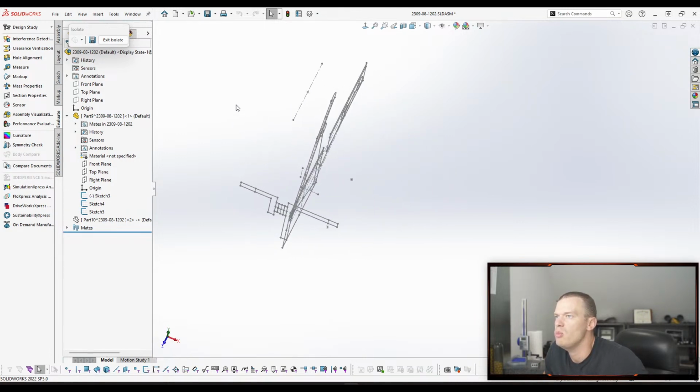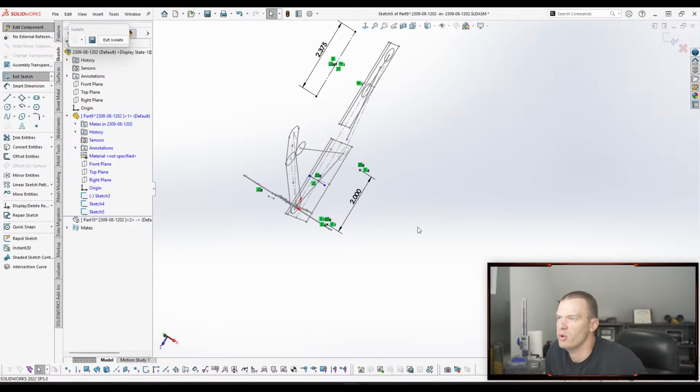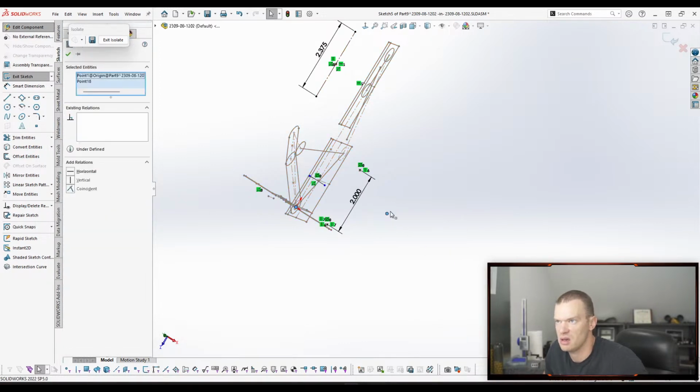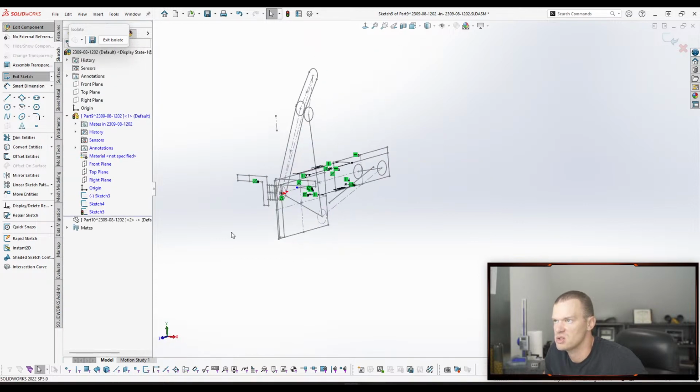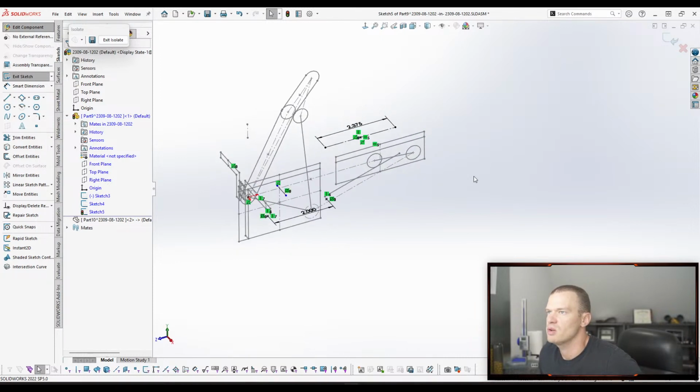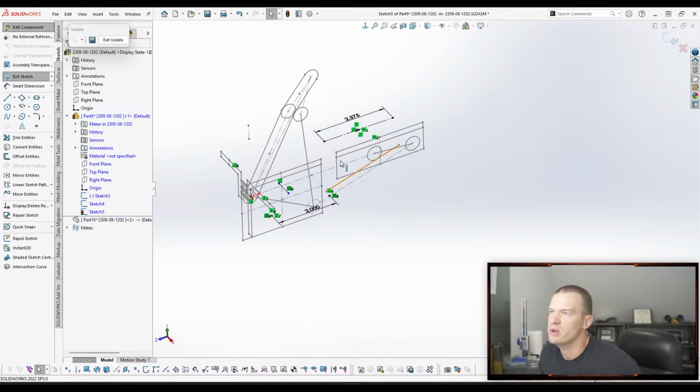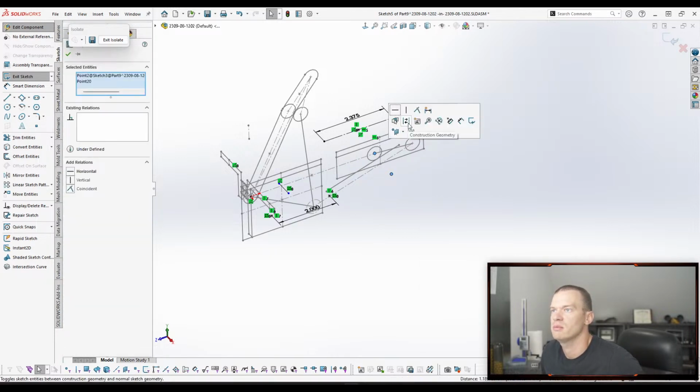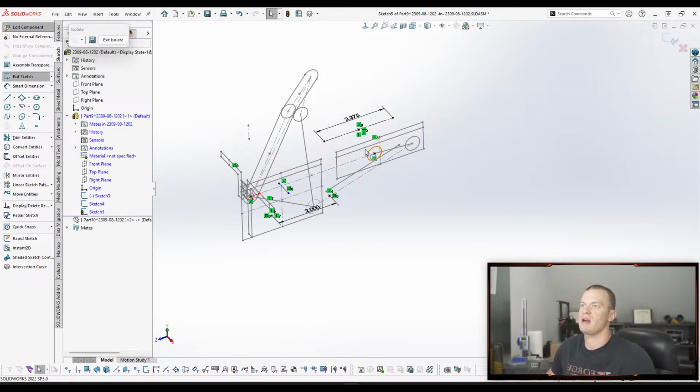All right, one more thing we want to add in here, actually, now that I think about it, is a point on the origin, so that when we go to align it later as a derived sketch, we have an easy way to align that. So we could put 2 origins in technically if we knew that we wanted this bracket designed in the way where the center point was going to go through here. So maybe we do that as well. That would probably be fine to do, right? Like, we want this to be a secondary option for the origin later, but we'll see.